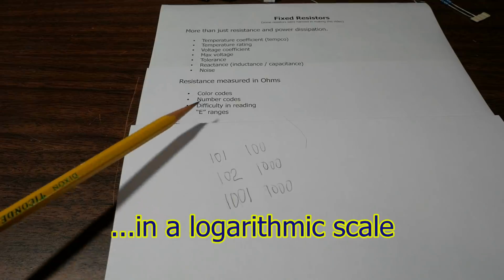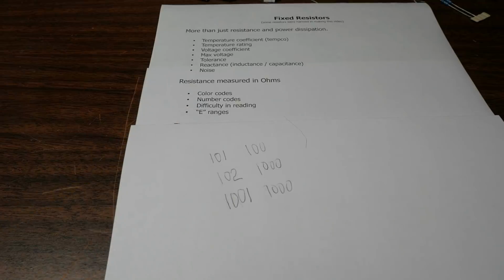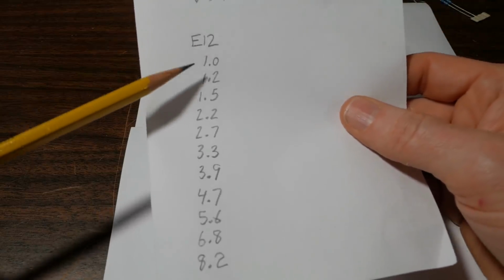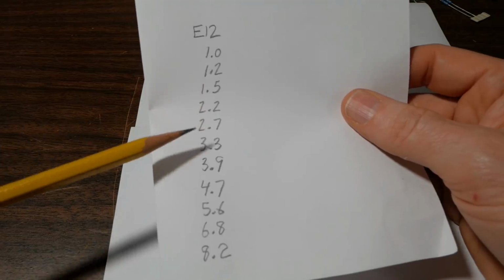For example, you'll have an E6 range. That means there'll be 6 different values per decade. You'll see an E12 or even an E24, where with E12 you'll have 12 different values per decade. So for example here, with the E12 range, you'll have all of these different values here.